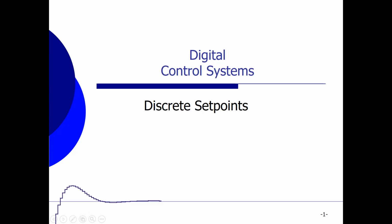Welcome to this video on discrete set points. If you want to position a system accurately, for instance in a robot application, you don't want to introduce infinitely high accelerations. After all, these create very high disturbance torques and forces, and that does not help in achieving high positional accuracy. In a second order set point profile, where the velocity is trapezoidal, the accelerations are bounded.